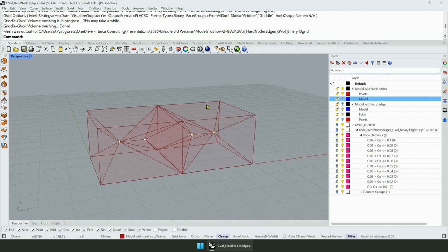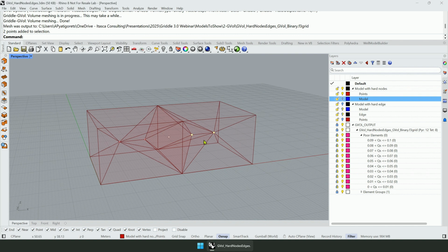And the reason for that is because volume mesh is non-interactive, same as with joint. I cannot select it. See, I can only select actual objects here. But this is done because when generating volume meshes for very large models containing, let's say, millions and tens of millions of elements, displaying and rendering real objects in Rhino viewports requires huge resources and may take significant amount of time.